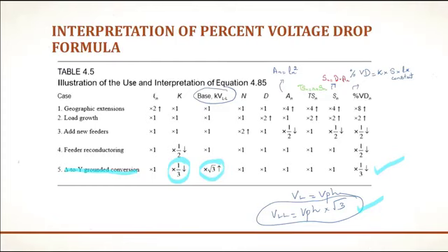These are the few results which you have seen as a result of performing different strategies for load growth, for geographic extension, for addition of new feeders, and for feeder reconducting. From a design and planning perspective, all these considerations are very important, as these cases give you deep insight into what the reaction of the performed action will be.